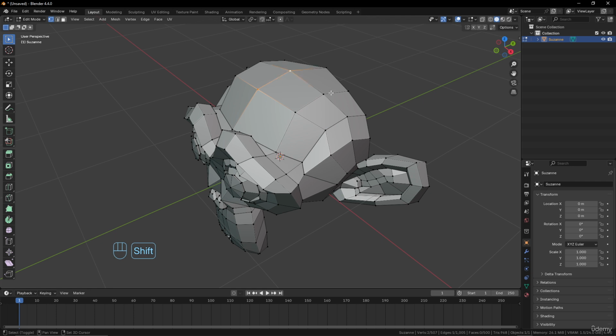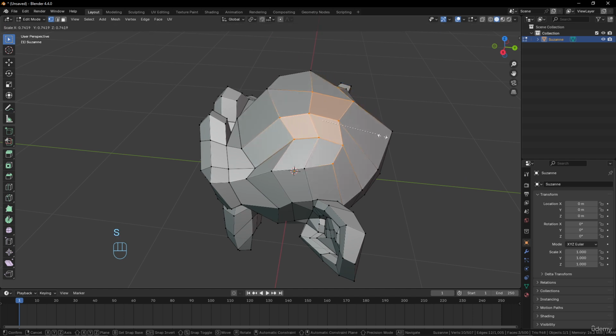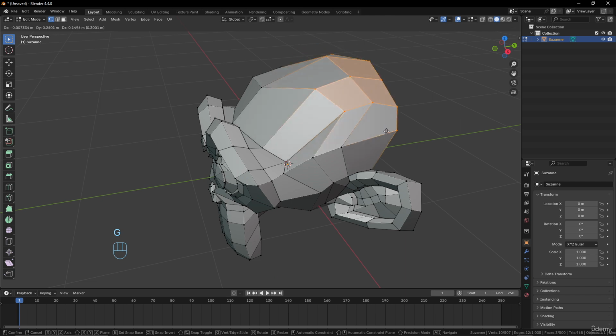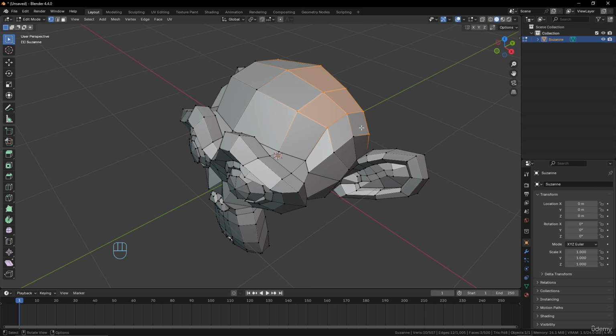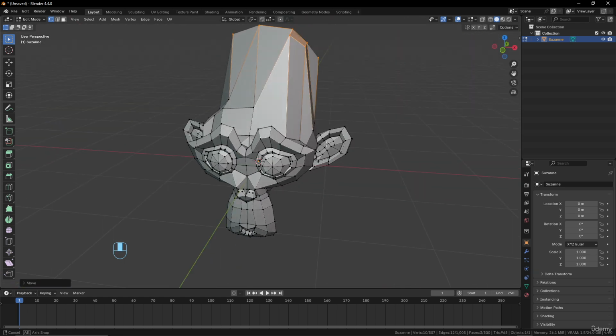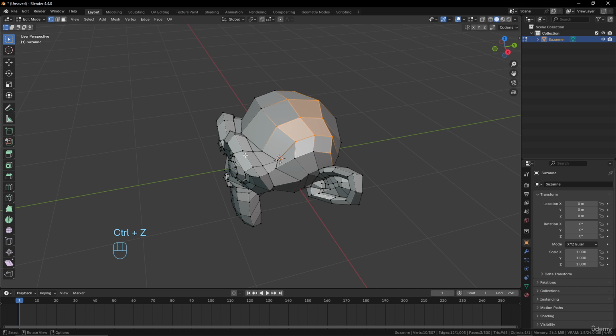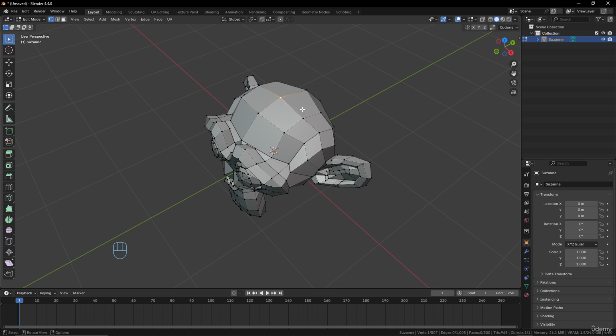If you select multiple vertices like that, you can scale the selection, you can rotate the selection, you can move it, and you can grab the selection with G as well. You can manage it with the same data that we used, with the axes and the numbers. If you want, for example, to move it on the Z axis by 1 meter, you will have this kind of behavior. So it's very easy to understand when you understand a little how object mode works.